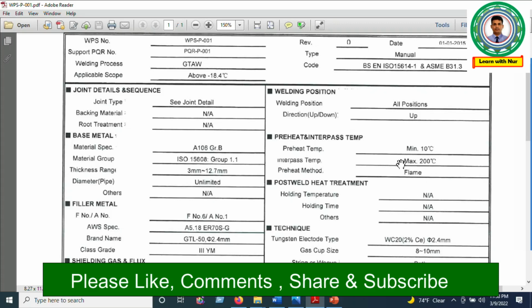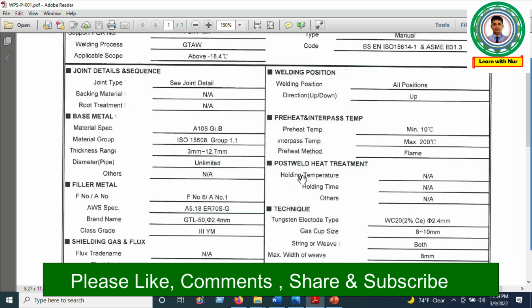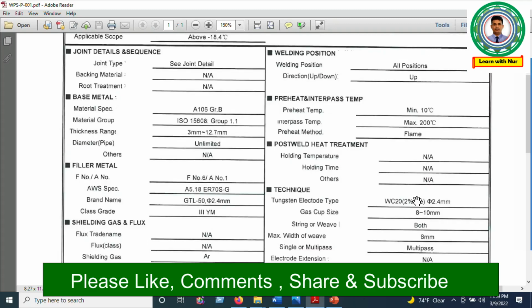so we have to use the flame heating torch. For preheating we need to use the flame type heating torch here. Then post weld heat treatment, PWHT, for the WPS: holding temperature not applicable, holding time not applicable, and others not applicable. So for this WPS, PWHT is not required.